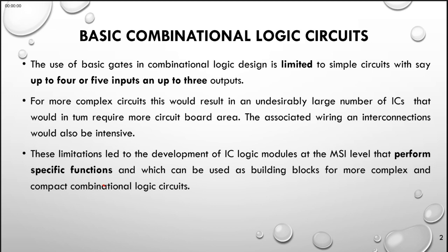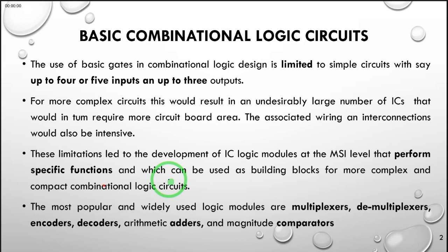MSI means medium scale integration. The development of these ICs has allowed building of more complex and compact combinational logic circuits. The most popular or widely used logic modules under the combinational logic circuits are multiplexers, demultiplexers, encoders, decoders, arithmetic adders, and magnitude comparators. You're going to be looking at these combinational logic circuits, their design, their use, and their operation.